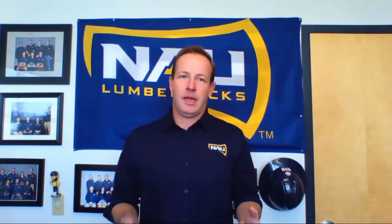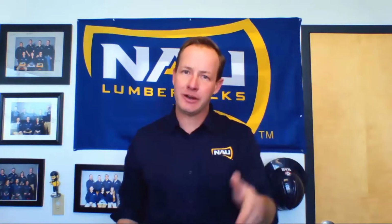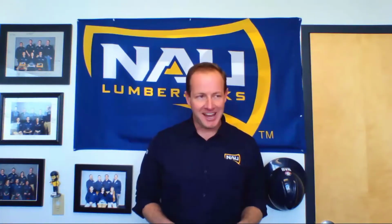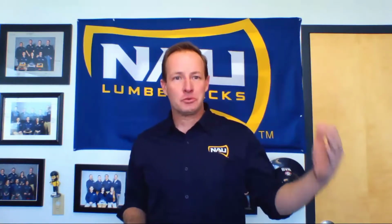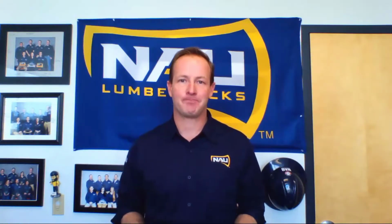Or they might have specified that they wanted this level of carpet quality or this type of carpet tile. And they didn't necessarily tell us which exact one they wanted. So now they want to look at them and they say, okay, I want that one. So they're clarifying. It's very important that you understand that it's not an opportunity for them to change things. Now, they will change things, okay? I'm not saying that they won't, because they will, and it'll get frustrating. But that's not the true purpose of submittals, okay?